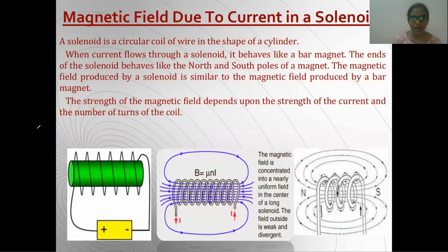Clock rule: when a current is going, which face are we going to see? Is the current going in an anti-clockwise direction or in a clockwise direction? If it is anti-clockwise, remember, anti means N will come, so write north pole here. Clockwise, it will be a south pole.